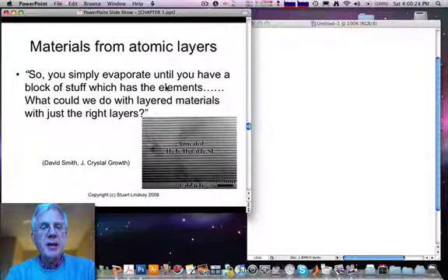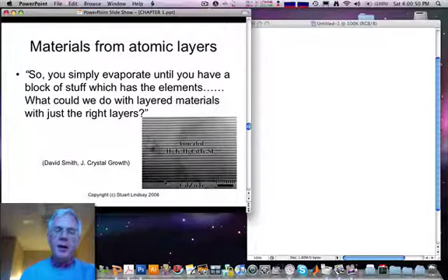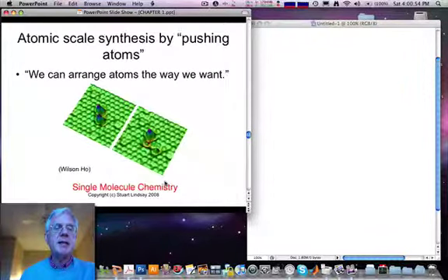The most common technique is called molecular beam epitaxy, and we will talk about this. In the electron micrograph you see here, the scale bar is 100 nanometers, and so these are layers of just a few nanometers thickness of mercury telluride and mercury cadmium telluride, and this whole thing is put together to have unique and special properties as a detector based on growing the structure with molecular beam epitaxy.